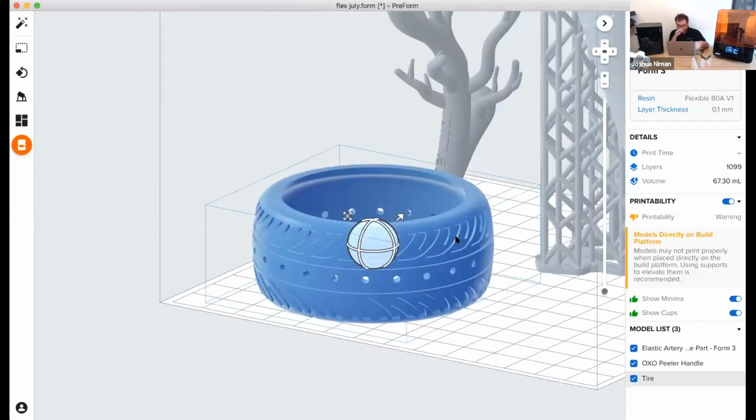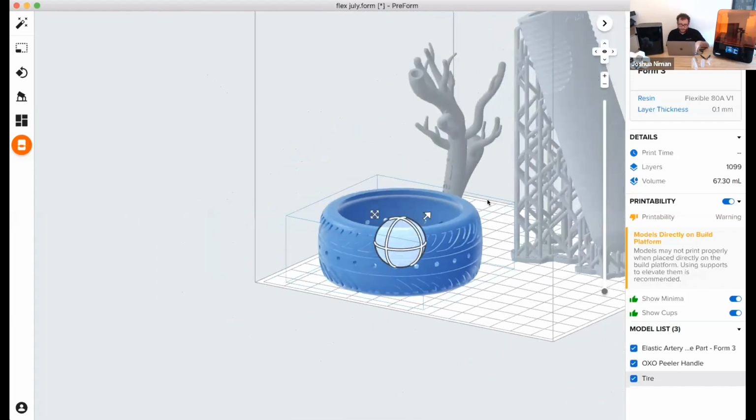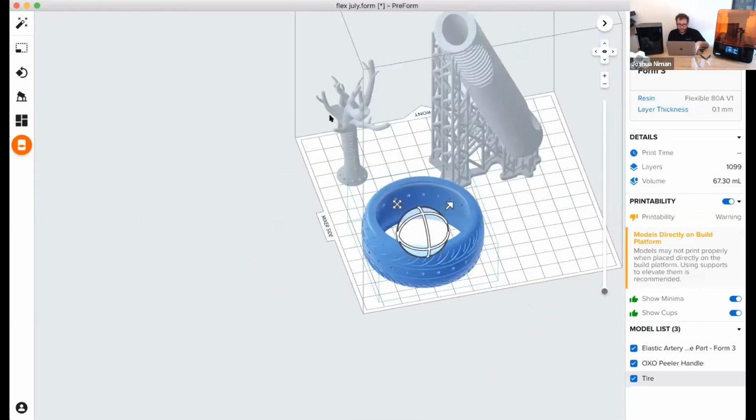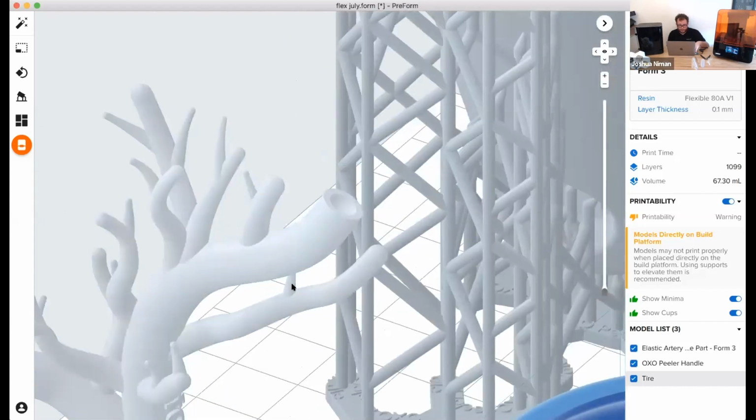And so, I think this is one of the first lessons to think about while printing with a soft material: there's always some force involved in printing. There's always some force being exerted on the part at some portion of the step, or in some step during the printing. And so how do we control where it's going to go? How do we relieve pressure anywhere we can? How do we avoid cups?